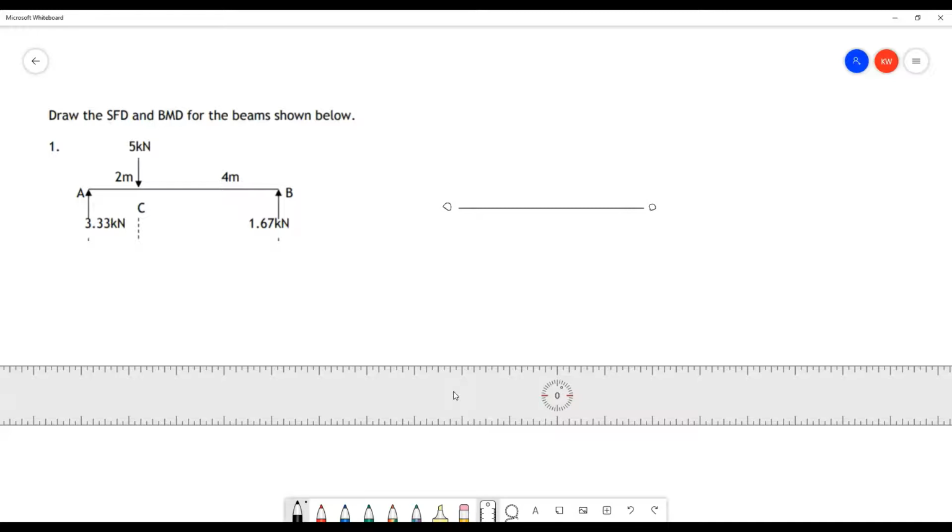If we attempt to draw a proper diagram, we will draw all of our lines so that they're proportionate in size. So a force of 2 would be twice as long a line as a force of 1 kilonewton. So we'll draw a line here and call this 3.33. I should be using a ruler, but I won't use the ruler for all of this. We've got a line coming up from 0, taking us up to 3.33 kilonewtons in the positive direction.